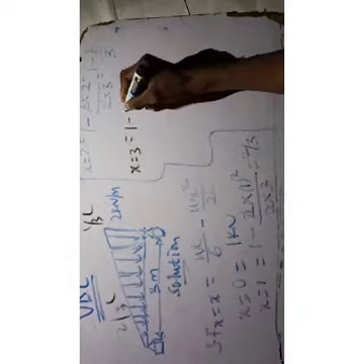And when X equals 3, which is the maximum point, you can have your shear force as 1 minus, W is 2 times X is 3 square over 2 times 3. This guy can cancel, this guy can cancel. 1 minus 3, that is minus 2.